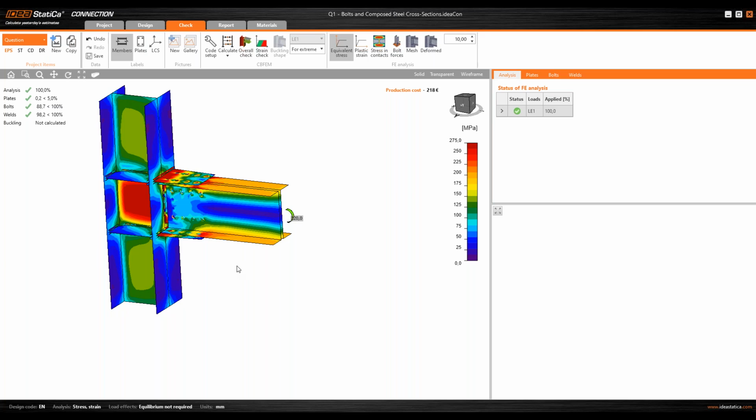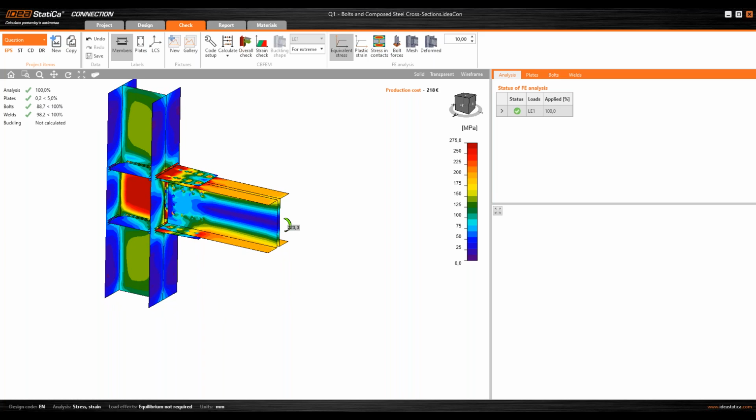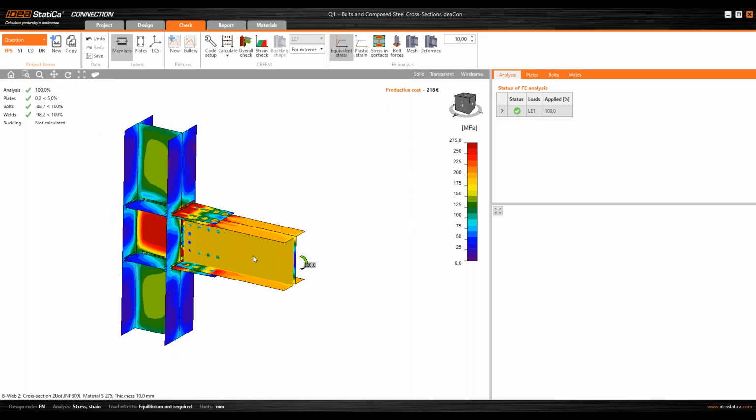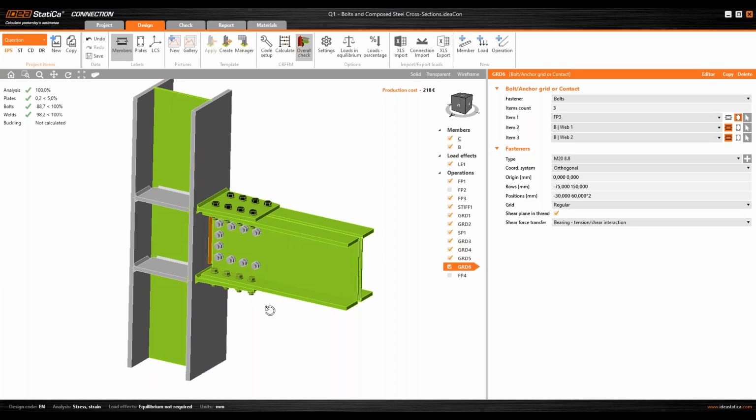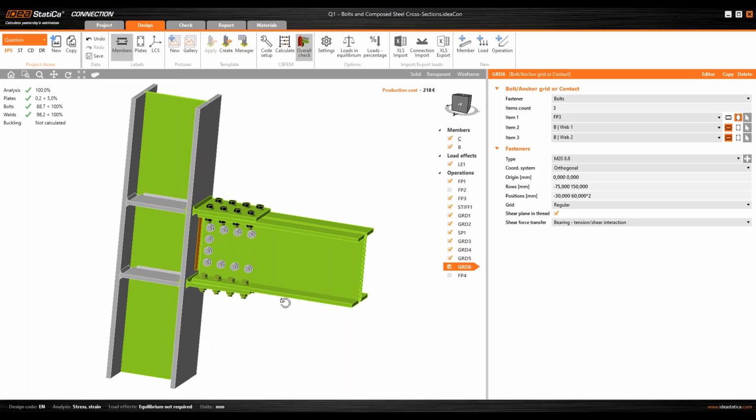If you could just sum up, what's the difference between using some specific operation like fin plate and the general one like stiffening plate, or why or when can we use one and when the other? Okay, it is a very interesting and complex question because as you can see, it is the same. There is no difference, and both methods, both templates or manual plates operation are perfectly valid.